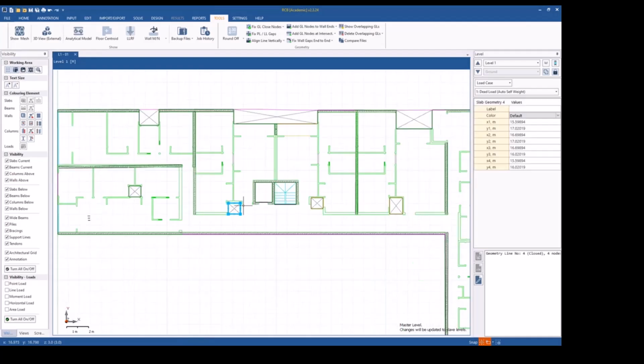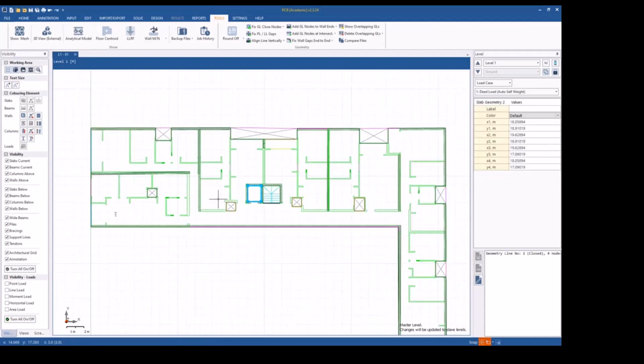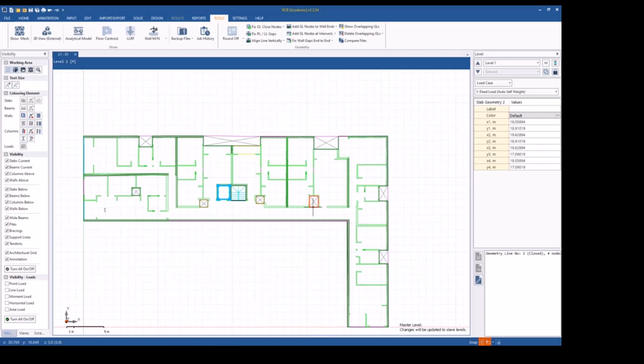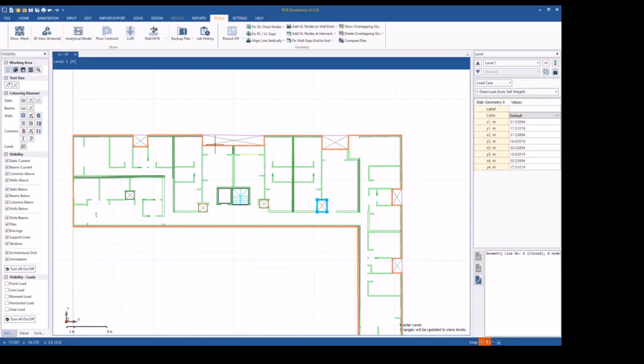We will be able to import thickness after meshing the slab. As we mesh the slab, we define it as a structural element to the software. So we need to mesh the slab. I'll show you how. Then we will be able to define thicknesses, and then the voids will be viewable.